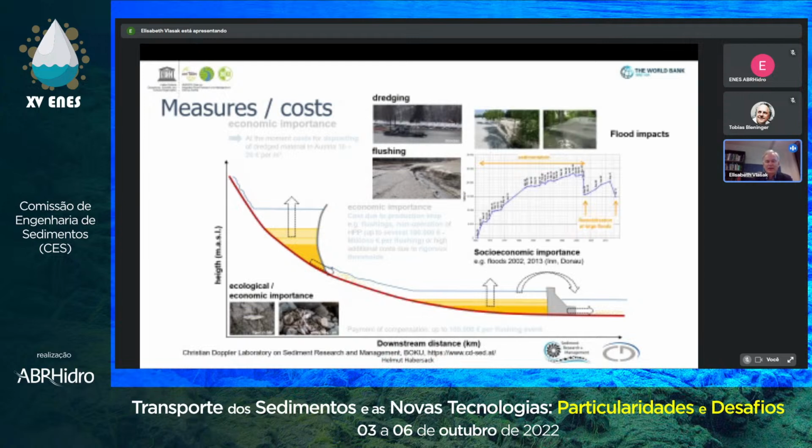And then we might have, like here, it is a little bit small, but you might have a sedimentation in a reservoir over 30 years or 40 years. And then you get a big flood, they open the gates, there's erosion here, and starting sedimentation again, and then you have a big erosion. Now, if you only do this unintended flushing, you might get sedimentation in the floodplains of meters, like we had here in two floods in 2002 and in 2013.